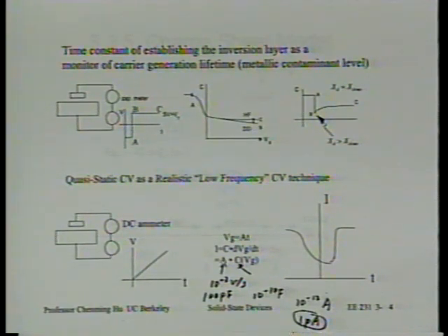Well, it has to do with thermal generation because it's the thermal generation that creates inversion charge, right? It takes several minutes for the inversion layer charge to be created. Now, if the thermal generation rate is higher than usual, that several minutes may become several seconds, right? Is that right? So that becomes the principle of this test, this monitor, okay?